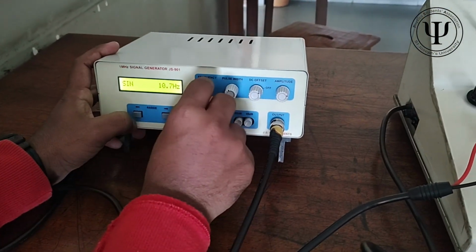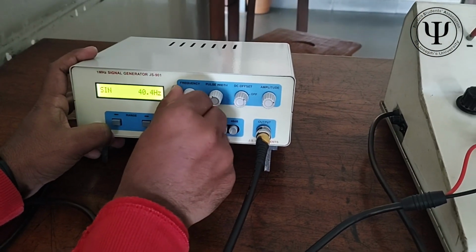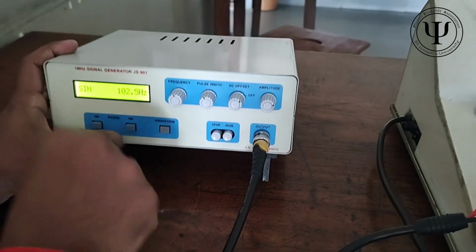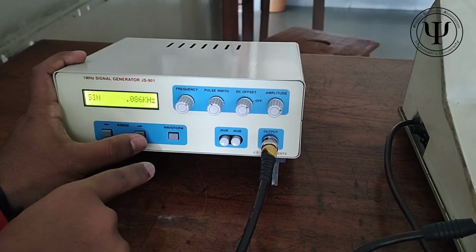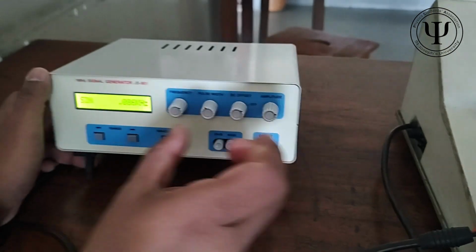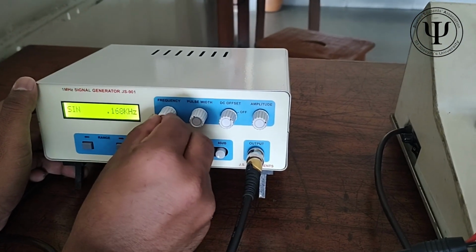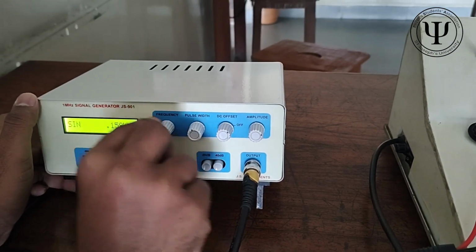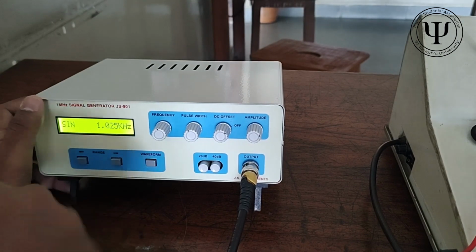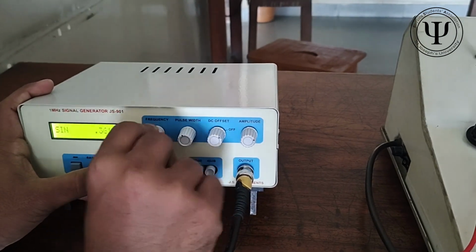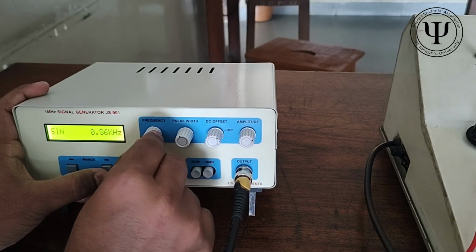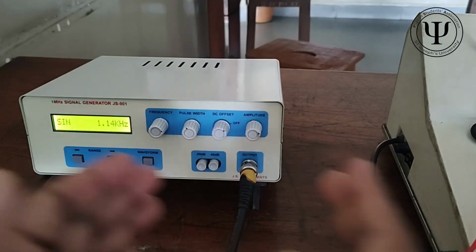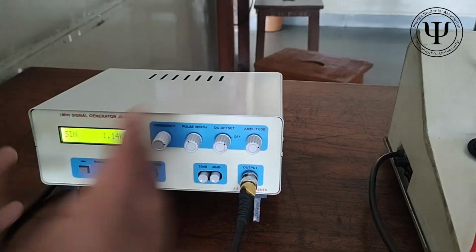So basically, you use this dial to change the frequency. Once it reaches the end, you cannot increase it more than 100 Hertz here. So what you do, you reduce the dial and you press this button. It goes to the next decimal, right? Now when you do this, it became 100 Hertz. When 100 Hertz comes here, it comes to this side of the dial. You increase it, it goes to 1 kilohertz. If you want to increase more than 1 kilohertz, you reduce it to 0, and the base will become 1 kilohertz. Did you understand? You are basically transposing the range.